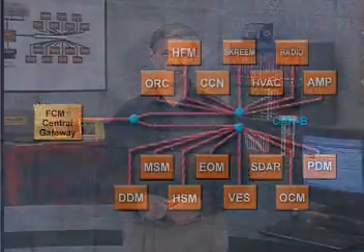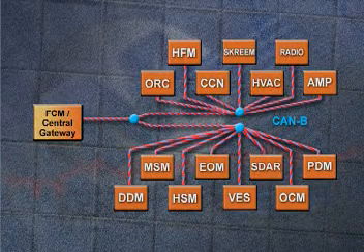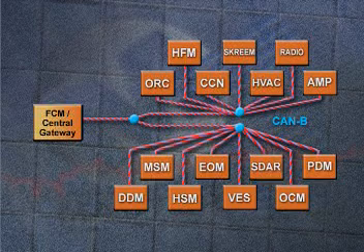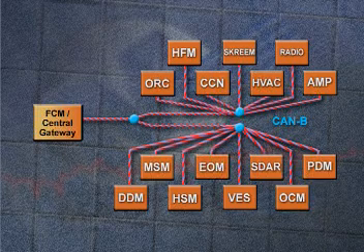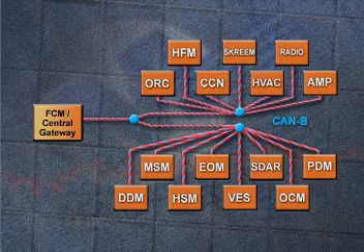In this segment, we're going to examine the individual buses that make up the Durango CAN bus system. Let's start with the bus which connects the greatest number of modules, CAN B. On Durango, the CAN B bus links a large number of electronic modules which control the body and safety systems shown here. See this month's reference book for a complete list of the modules on the CAN B bus.